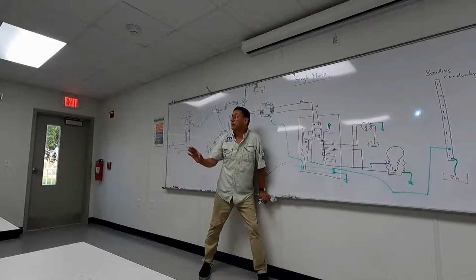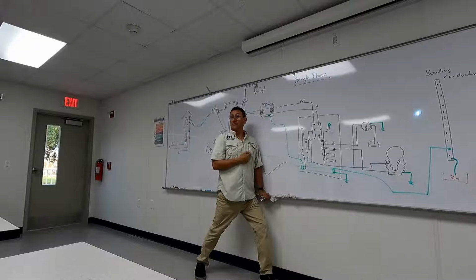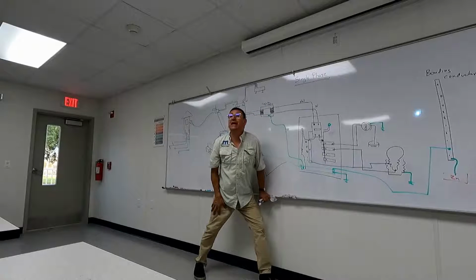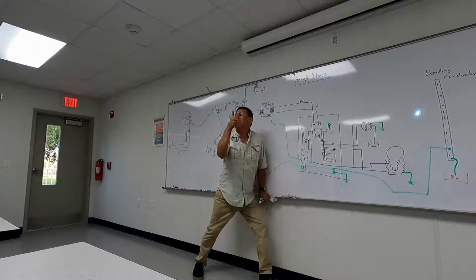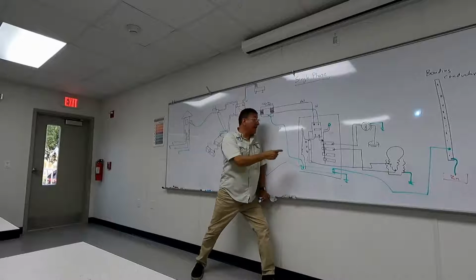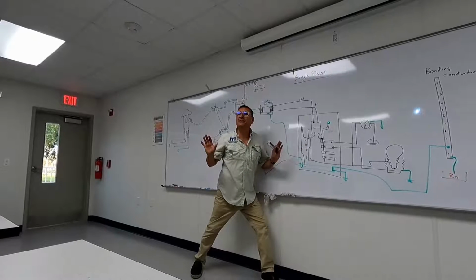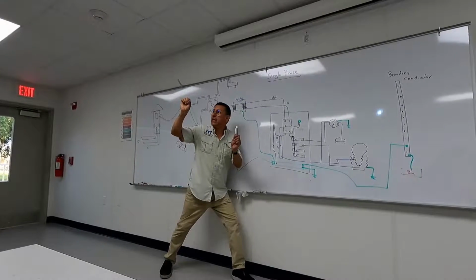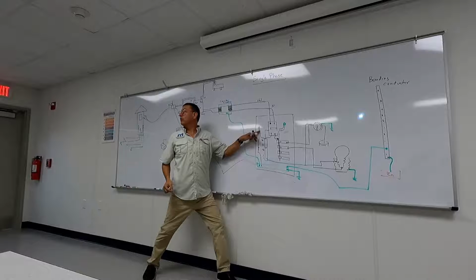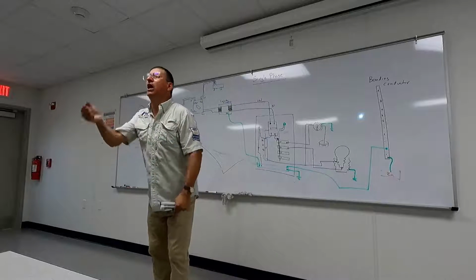If you switch those cables, the neutral is hot. I have hot and ground. I have voltage, no? You remember that when you read between hot and ground, it's a little less, but it's voltage. How is the light right now? On, because my neutral right now is hot.